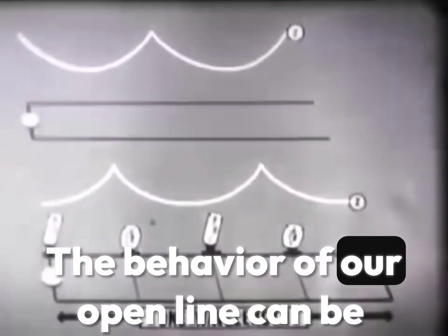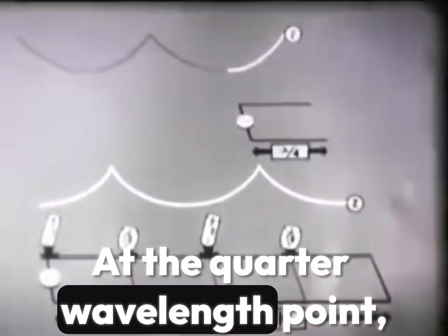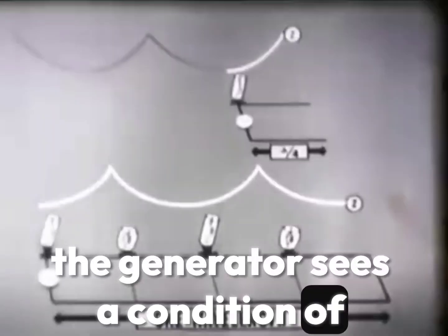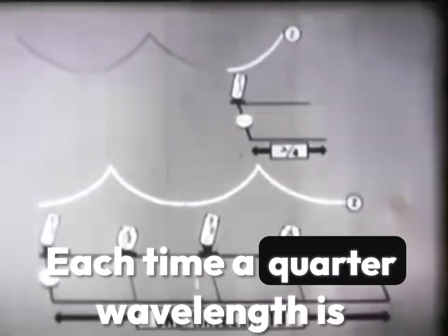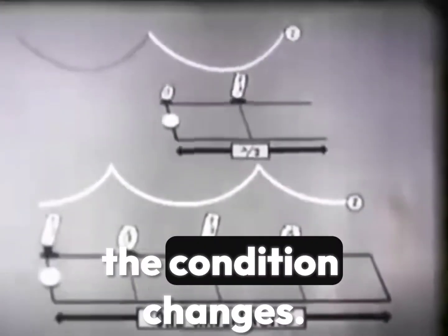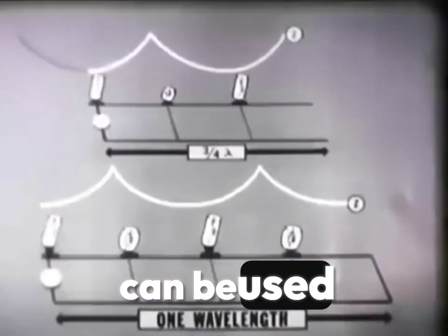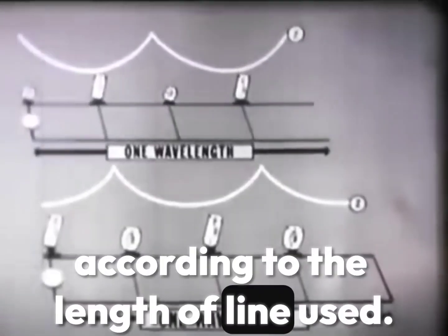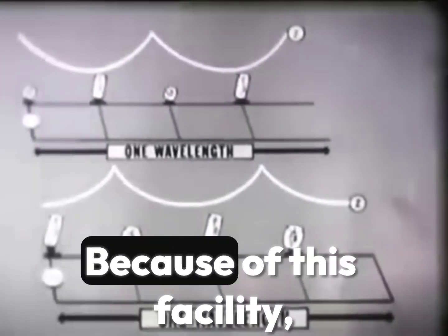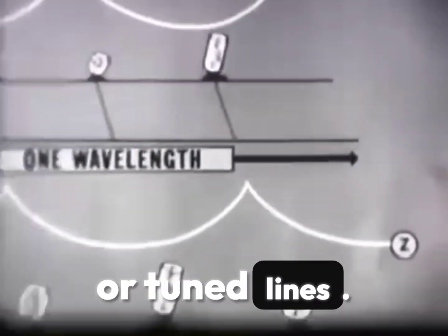The behavior of our open line can be investigated in the same manner. At the 1/4 wavelength point, the generator sees a condition of minimum impedance. This circuit can then be considered a series resonant circuit. Each time a 1/4 wavelength is added to the circuit, the condition changes. Thus, open and closed-end lines can be used as parallel or series resonant circuits, according to the length of line used. Because of this facility, they are known as resonant lines or tuned lines.